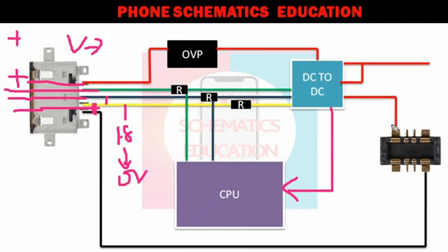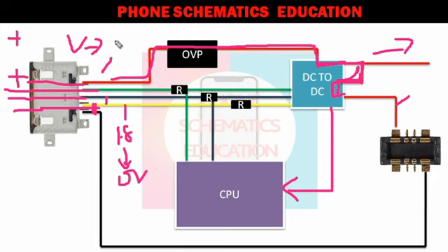Now, through this point, when you remove the charger, your phone runs on the battery. Here is a MOSFET. So this MOSFET works in reverse. Now your battery at the same time runs the phone. Also the same battery power, through this line on the OTG connection, through the IC, through the OVP, this line gets 5 volt here to run the OTG. I hope you will get it.